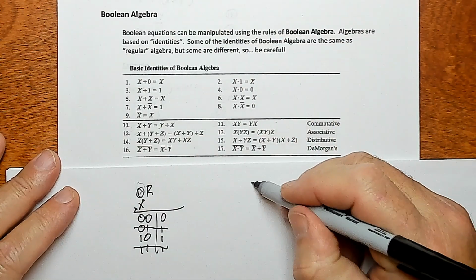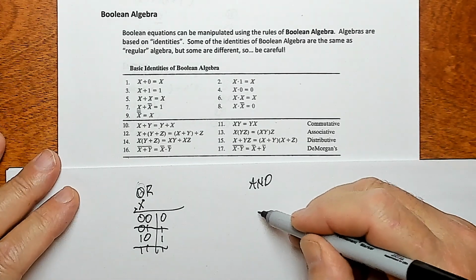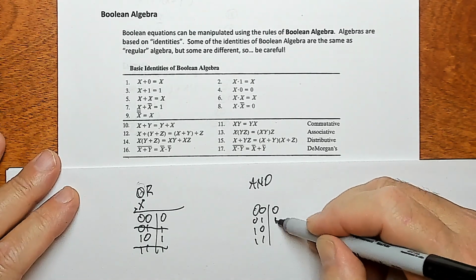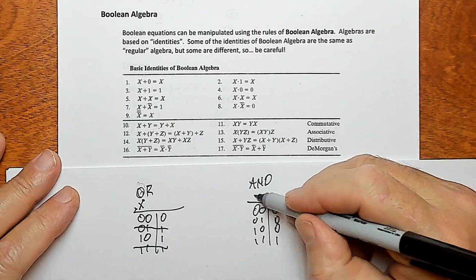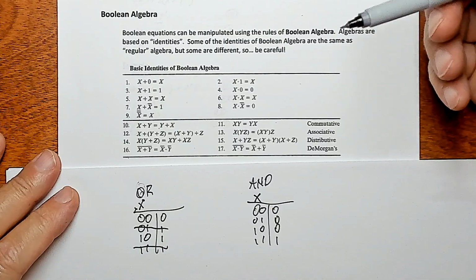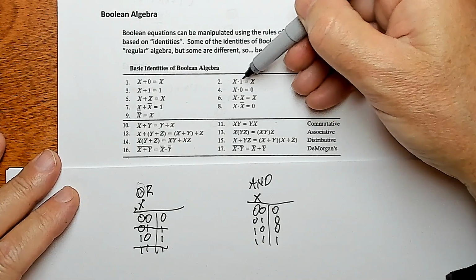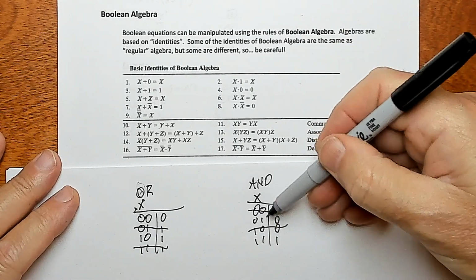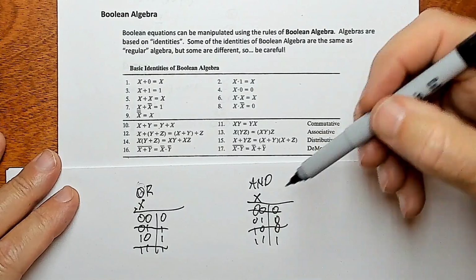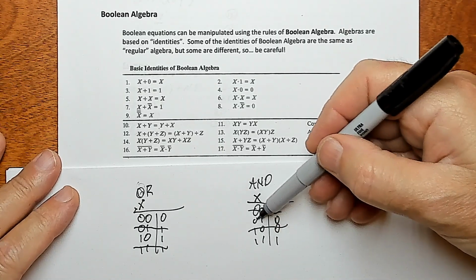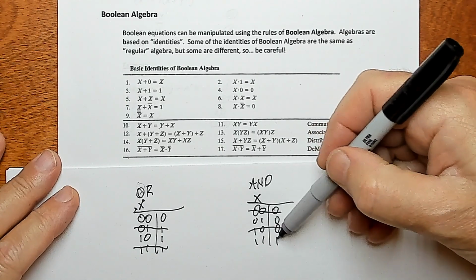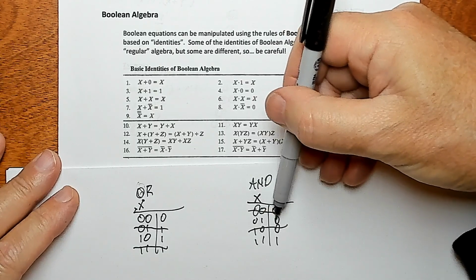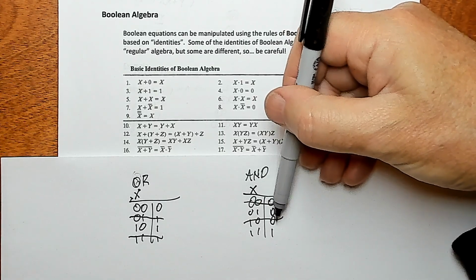You could prove AND the same way. Here's the definition of AND. First, the input side, then the output side. The output side of AND is this. So if we make x this, then we're saying we're ANDing x with 1. So let's cross out the rows where the other operand is 0. Cross out these two rows. So if x is 0, you get a 0. If x is 1, you get a 1, which is, whatever x is going in, that's what's going to come out. That's what this is saying. So, it works.